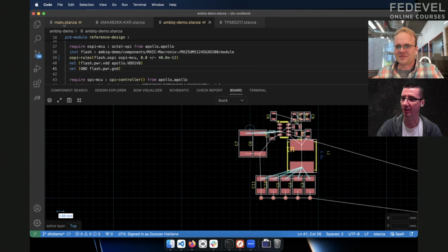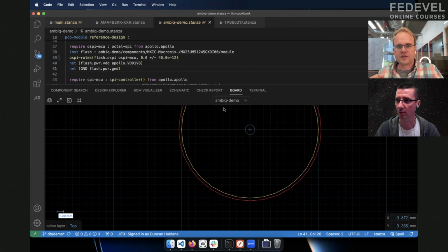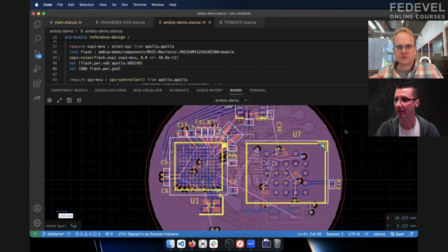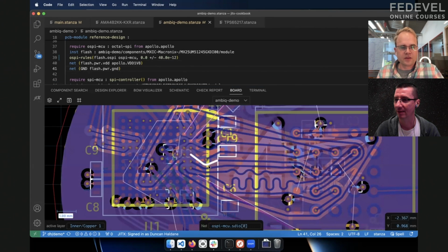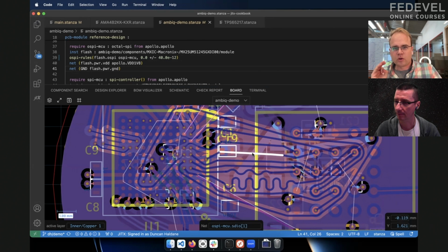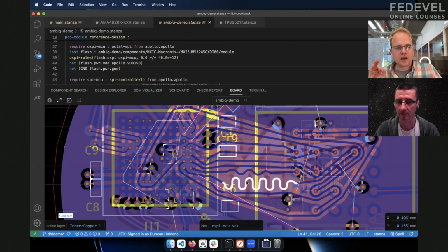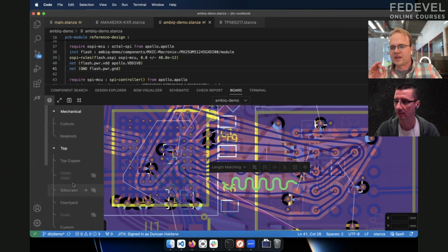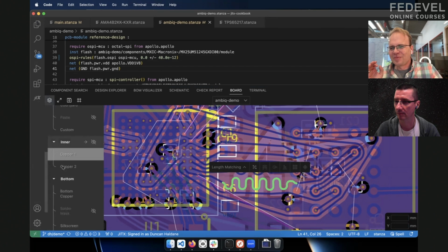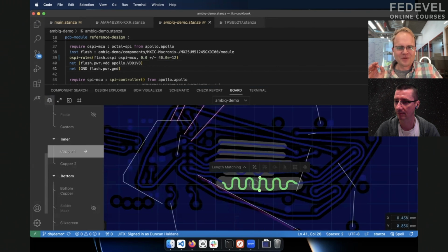Can we go back to the previous design? Is it difficult to show, let's say, the length matching of the SPI interface? I know we don't have to do length matching for SPI. I just would like to understand how difficult it is. Well, for OctoSPI, I think you want to hit a window. So the model here is the same one we use for DDR, which is, let me isolate this layer. You probably have better ideas about how to route this. We're going to drag a via.